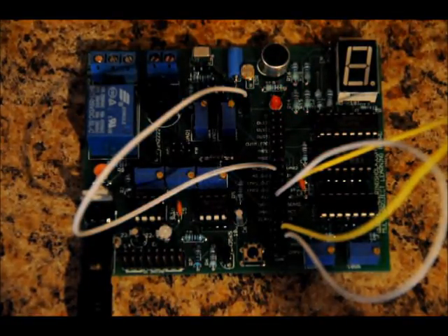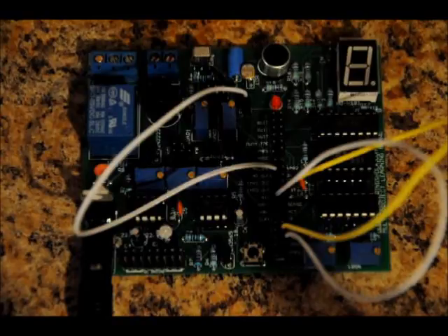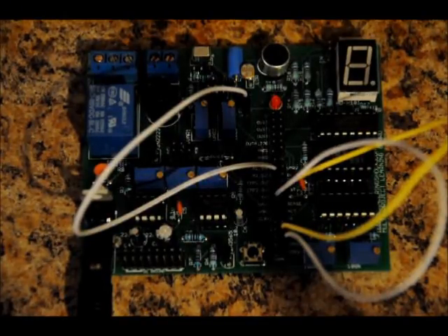So, when we have light on the LDR, we've got roughly 0.45 volts on our sense line, and that's going to our positive input. And we've got a dedicated 2.5 volts on our negative input. So when there's a lot of light on the LDR, there's more voltage on the negative than the positive. And when I turn out the light, the resistance on the LDR goes up, and the voltage on the sense line goes up, and it exceeds 2.5 volts, which is on the negative line. So we get more than 4 volts on the positive line. There's 2.5 volts calibrated on our negative line, so our LED turns on.